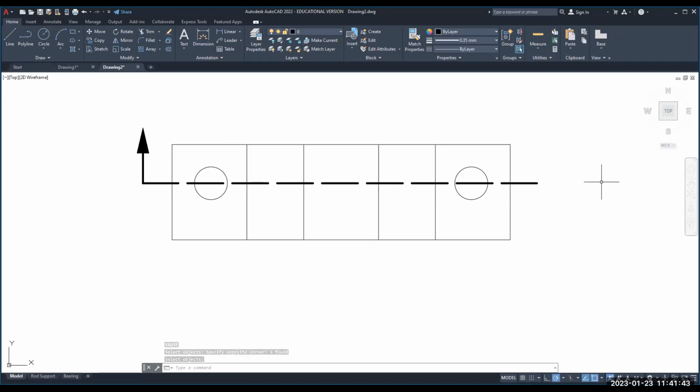But is there a way? You can put in a dimension for that drag. Yeah, but I wouldn't. This is what I'd do: I'd pick the one I liked and just go copy. Right. And then take it and set it over here. Now I have them exactly the same. And if I needed more, I would just keep copying them, rotate them. Once you're happy, then you don't have to use polyline.